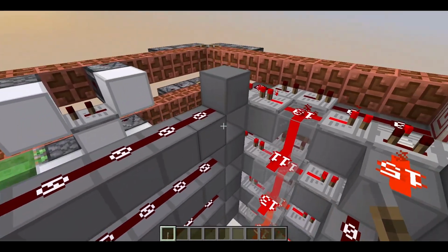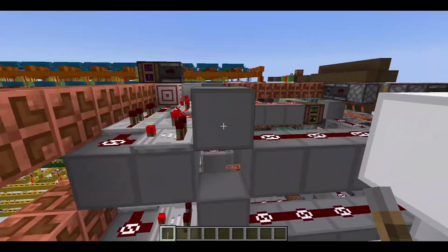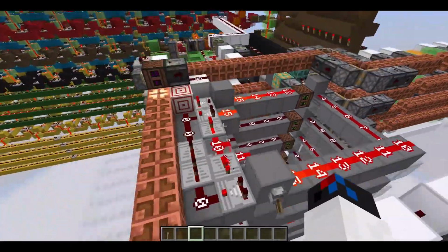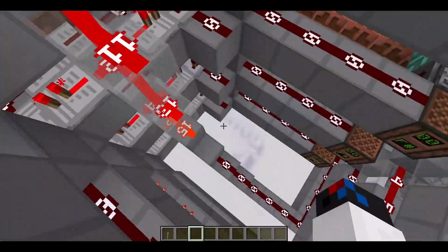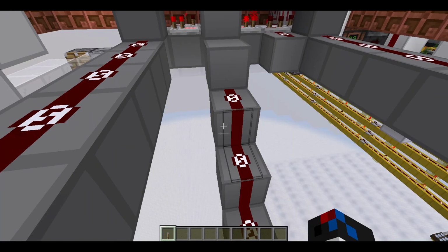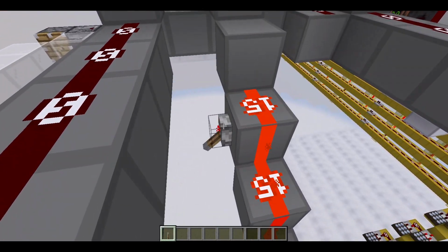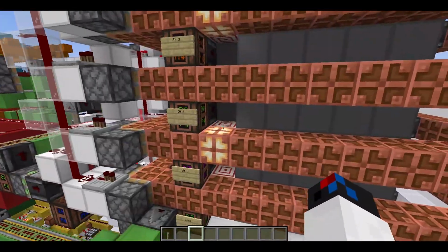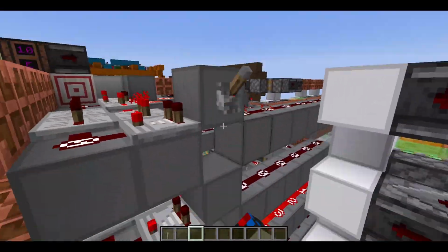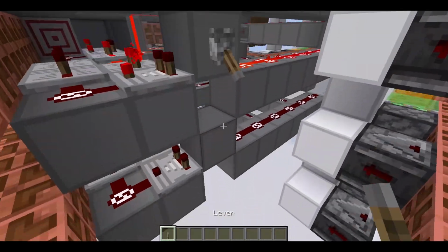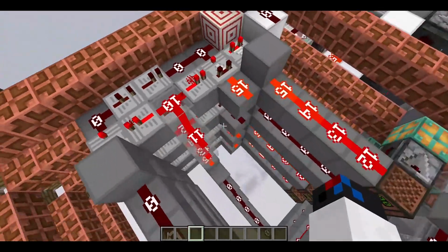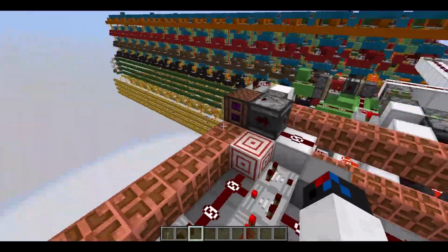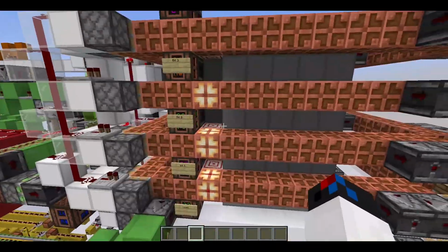So let's say I want to send, I don't know, this number, which is 10 in binary. And now if I activate this line briefly, like this, as you can see, now we have a 10 here. And if I change this to, let's say, 7 in binary, and then I do this, we should get a 7, as you can see.